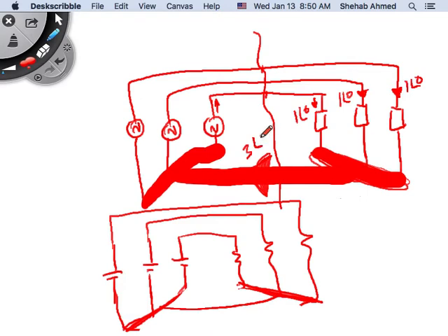3 amp angle 0, right? But if I look at how I can utilize the benefit of a 3-phase AC system: if it's a DC system, I don't have a choice. I will end up having to put a thick conductor here that is going to carry 3 times the current, right?